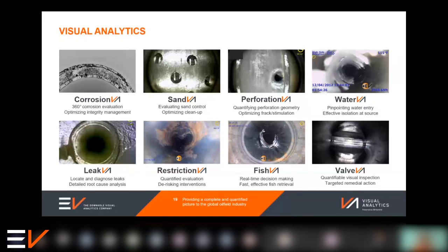It has a profile on the outside and a clean bore down the center. So whether you choose to go in with another overshot or a spear down the center, you've got both options. But the key thing is we come back out of there with the video camera. So even as we're extracting it from the release mechanism, we can see what's gone on, and you can even then see the condition of the dressed fish that you've left behind.